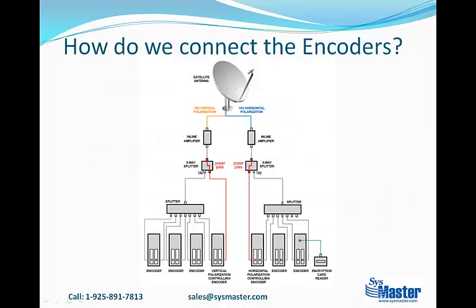So how do we connect to encoders? Most internet TV providers capture the channels from satellite dishes. Most satellites typically broadcast hundreds of channels, but the providers may be interested in capturing only some of them. Channel owners and satellite providers publish the frequencies, the transponder, of the channels and the polarization. Shown in the diagram is a typical setup for an internet TV provider with multiple encoders to capture channels on different transponders. If the channels are encrypted, we have a facility to decrypt the channels using card readers.